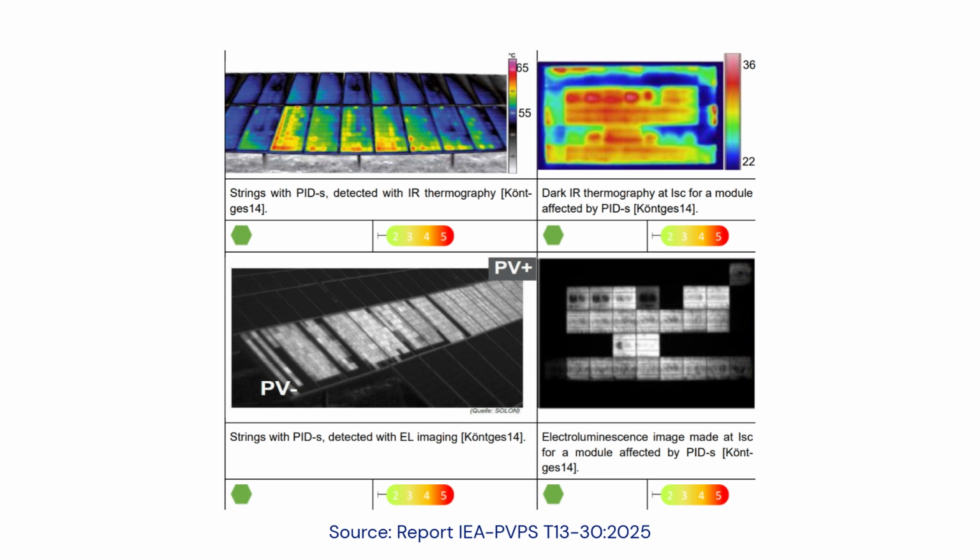Potential-induced degradation is a degradation mode induced by a high voltage stress with respect to ground. The occurrence of this failure depends on the magnitude of the voltage, number of serially connected solar modules per string, and the polarity of the electrical field buildup between the framing and glass surface and the solar cells. The last depends on the inverter typology, transformer, the grounding concept, and cell technology.